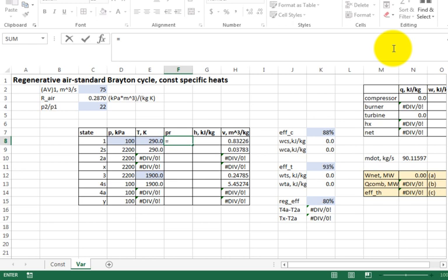And you just say PR_T. What's that doing? You can see what they're doing. They're suggesting, are you trying to get to these functions that are built in and have some add-in? And so it's PR_T for air. And when I see it, I just hit tab, and so now it's ready. So I want PR. I'm going to feed it T for the air tables. So I feed it this cell right there. Cell E8 has my temperature in Kelvin.